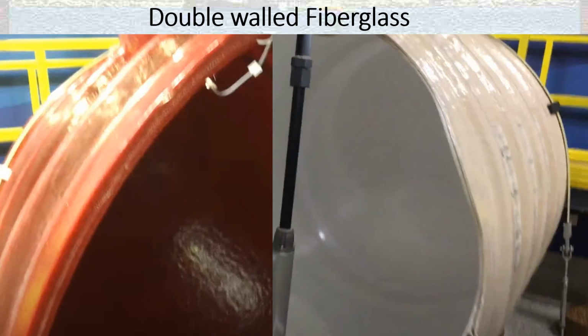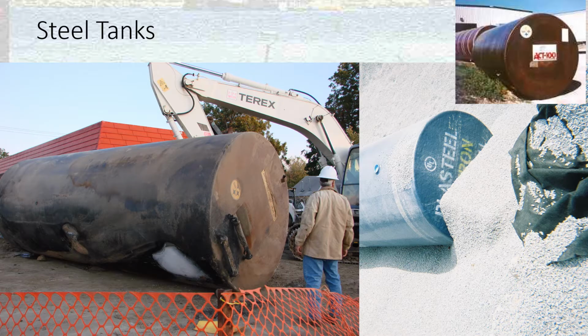And these are some views. I always had trouble picturing what the interstitial space for a fiberglass tank looked like. And you can see here there's kind of a mesh material that goes between the primary tank and the secondary tank, and that's to allow any liquids to move between the 2 tanks so that it can be detected through your release detection device. You can see over here in the other tanks it's the same concept. You just have an interior wall and an exterior wall and a space between that you can monitor so you can catch any leaks.